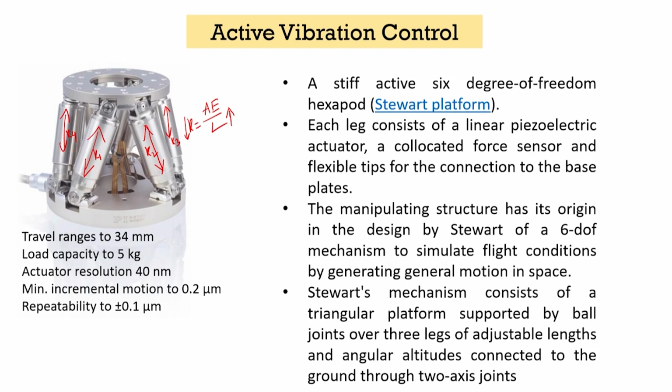What is the advantage of it? Well, this is particularly used for rockets. If there is a vibration coming from here, then by controlling the frequency, you can create a band gap, so that those frequencies, if the system is very steep and the frequency is low, will not be able to transmit. So, the satellite or the payload sitting here will remain insulated from whatever is happening at this end of the system. So, that is a Stewart platform application.